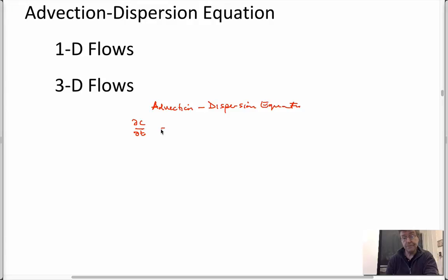We have an accumulation term. We have a term that acts on concentration to say how it spreads out as we flow longitudinally. We have a term that represents how it spreads out in the transverse mode as we go downstream, if you like, from a plume. And we have an effect which is to advect it downstream. And so each of these terms, this is advection by definition.